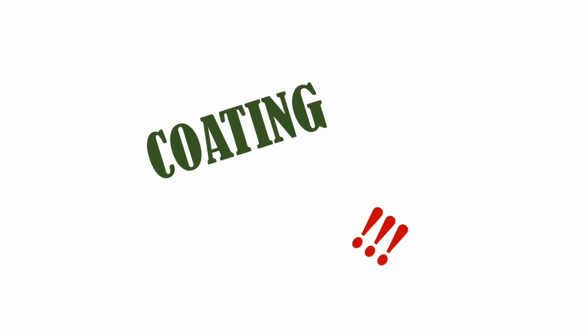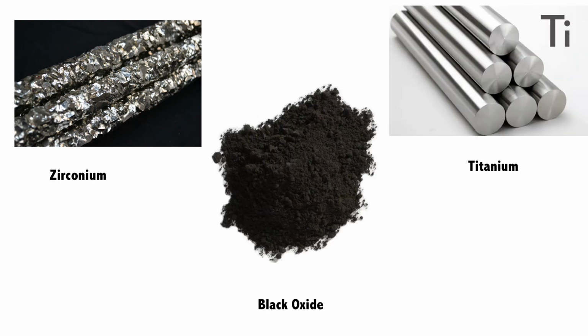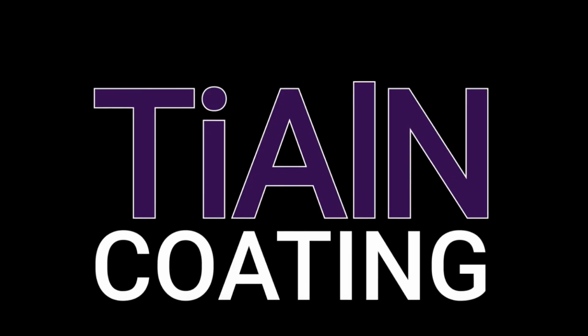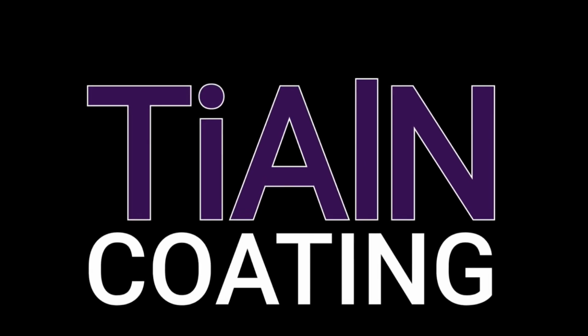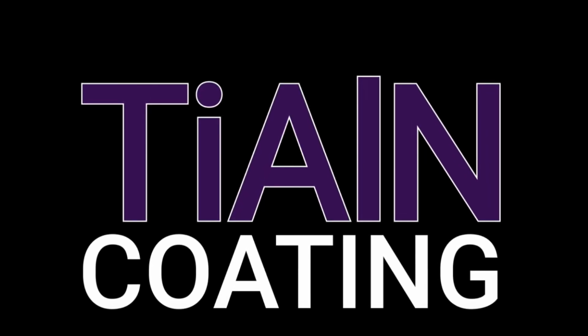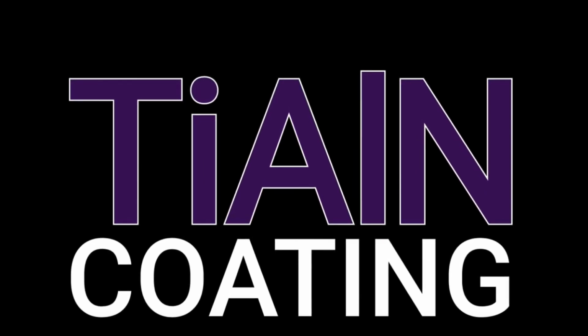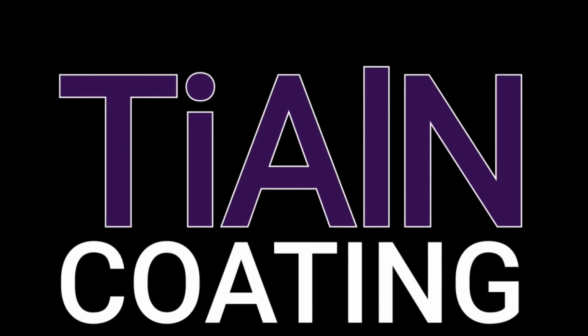For a drill bit, coatings are important. There are 3 main types for drill bits: zirconium, black oxide, and titanium. Titanium coatings are typically the hardest and provide the most protection, thus will be the ideal coating for this case. Specifically, titanium aluminum nitride has a high heat limit and increases edge hardness, which will prolong the lifespan of the bit. TiAlN is the hardest coating, thus will be the optimal for this case. In cases of drilling into aluminum, TiCN will be preferred.